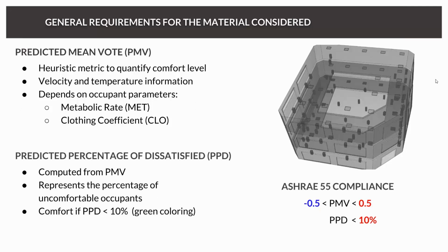And the reason why we need PMV and we cannot just use the temperature is that there is a difference between the actual physical temperature and, let's say, the comfort temperature. And whether we feel that it's comfortable depends on the combination of temperature and velocity. And this is something I think most of you can easily understand. It's something different to sit in the garden at 15 degrees if it's wind still and sunny, or if it's, you know, very windy.